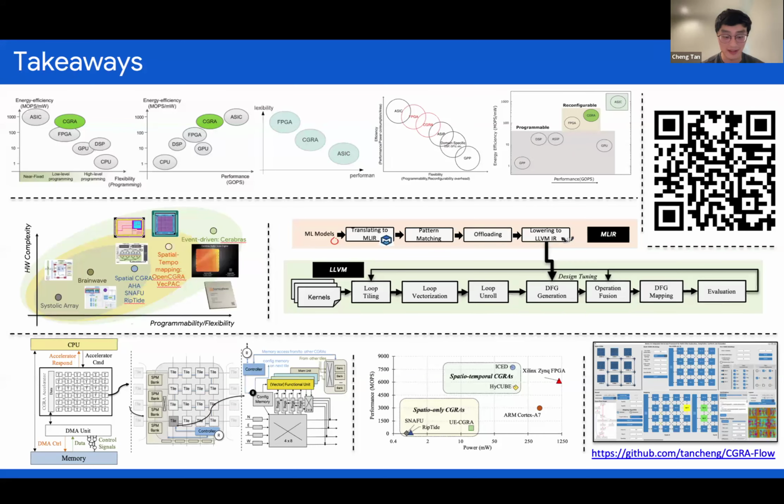If it's a compute intensive kernel, it is probably suitable for instruction level parallelism or loop pipelining. But if it's data intensive, then we need to put some effort into the memory hierarchy, or how the CGRA integrates with the SRAM or DRAM, or communicates with the host or other heterogeneous IPs in the SoC. That may be a new requirement for accelerating data intensive applications. That's my opinion.